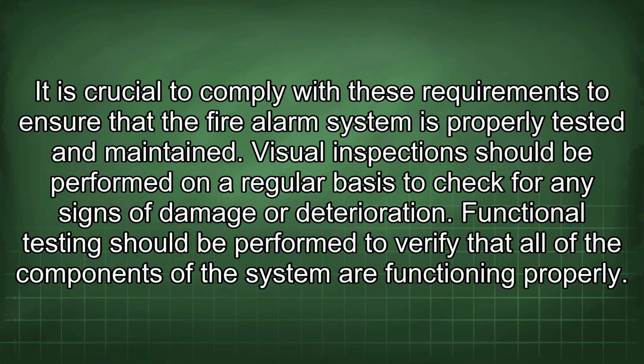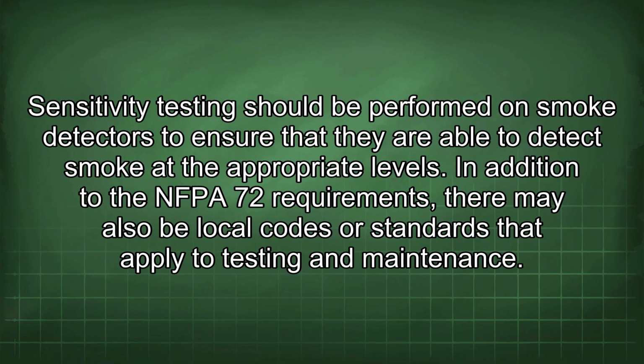Visual inspections should be performed on a regular basis to check for any signs of damage or deterioration. Functional testing should be performed to verify that all of the components of the system are functioning properly. Sensitivity testing should be performed on smoke detectors to ensure that they are able to detect smoke at the appropriate levels.